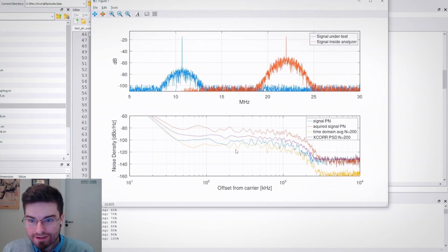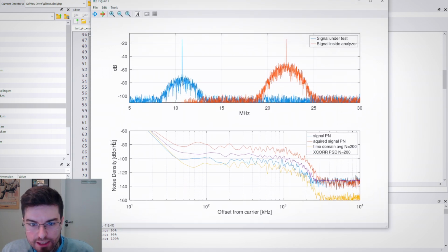And if we plot here, guys, look at this. Here we have the phase noise in dBc, and here is the offset. Here is the distance from the main tone. So actually, when we look at this plot here, we are looking at the left side of the signal. You can imagine that the main tone is here at the side, and we are measuring the power on the side bands. So look at this. This blue phase noise profile here is the noise of the oscillator we are trying to measure. But look, the analyzer is looking at the orange signal that has a greater phase noise because the measurement equipment is corrupting the measurement.